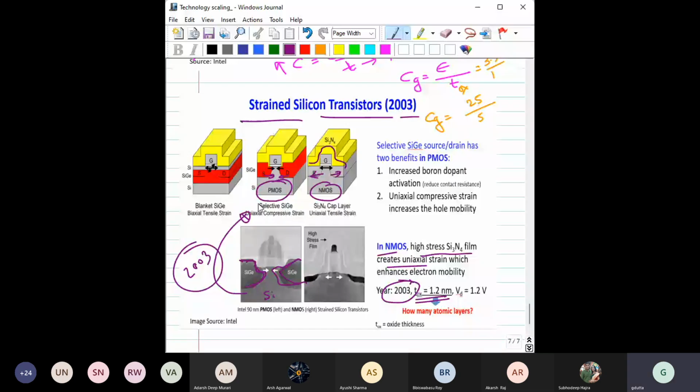As a result, there are power dissipations, on-state power dissipation and off-state power dissipation. For these devices, off-state power dissipation is dominating, not the on-state. We have seen on-state power dissipation, right? And the switching loss and all this loss. But for this type of devices, because now you are considering so many devices, if they are off, then there will be billions of transistors that are off. If the leakage current is very tiny also, then the power dissipation combining for the total microprocessor or the total circuit is huge, right? So with this, we'll stop.